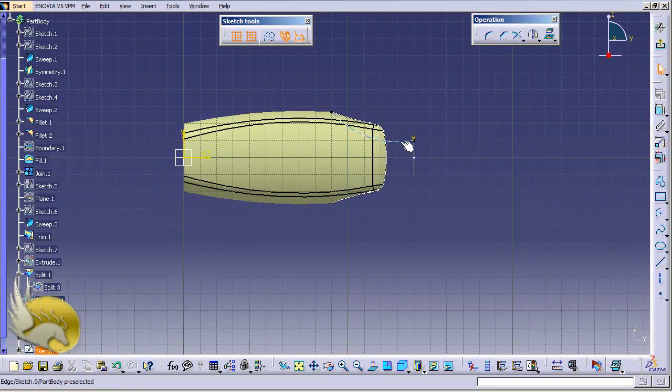So first of all, I click on this sketch and project this into this environment in 3D. Now by projecting this, I can make it go to the other side by using the symmetry tool. In the operation, I select the symmetry and select this horizontal axis. Now I can see that the actual arc is created on the other side, and they are exactly the same. They are touching the circle and the boundary at the two ends. So I exit my workbench.